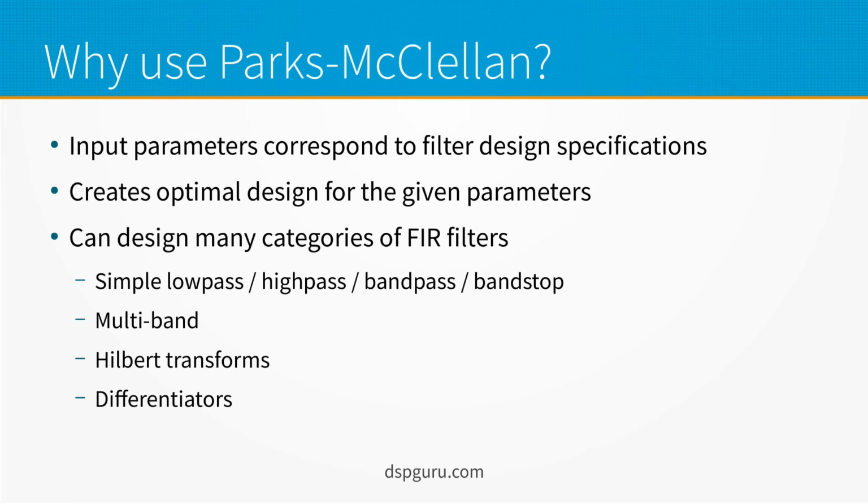The most obvious ones are the simple low-pass, high-pass, bandpass, and bandstop filters. It can also design multi-band filters, that is, filters that have multiple pass bands or stop bands. And it can design Hilbert transforms that are useful for creating complex signals. You can also design differentiators, although that's not a commonly used application anymore.